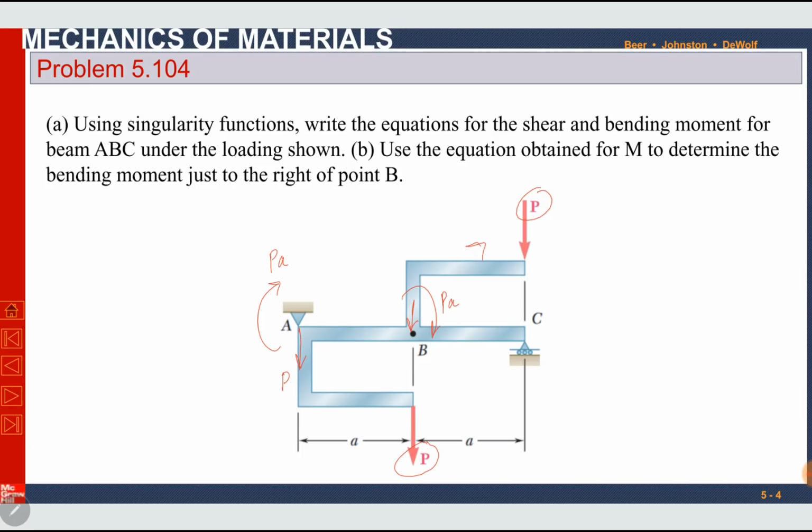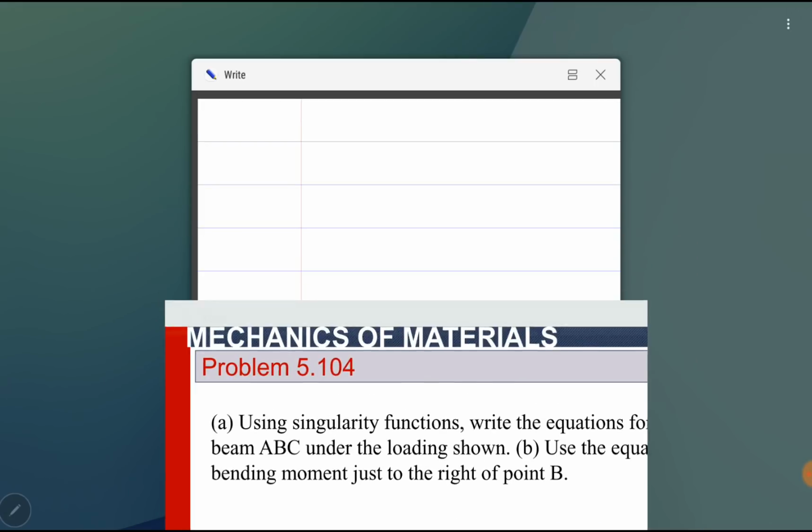So there are reaction forces as well at point C and point A. At point C there is a reaction RC and at point A there is a reaction RA. So the reaction force RA and the force P at point A, they both can be added again after calculating both these values. First I will find the reaction at A. We will draw a free body diagram.